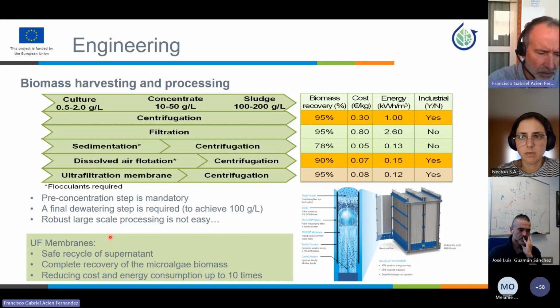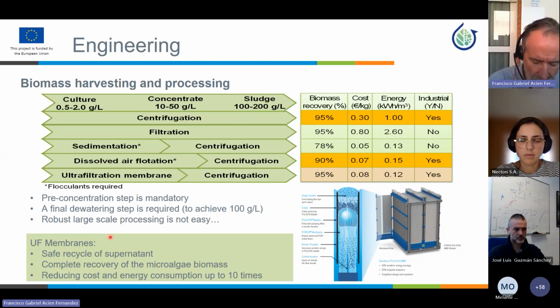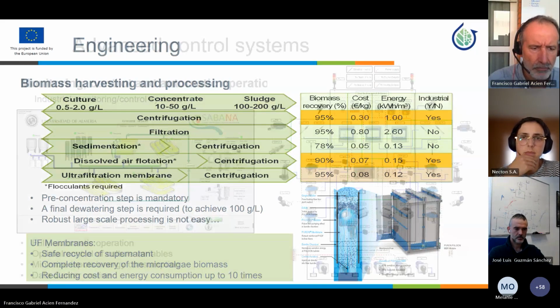One important question for microalgae reactors is also harvesting and processing of the biomass. The most conventional technology is to use centrifugation, but we must think that centrifugation is really costly and also consumes too much energy. Then we need to develop low-cost technologies integrating preconcentration and further dewatering of the microalgae biomass. We believe that the use of membranes can really be an opportunity for this type of technologies.